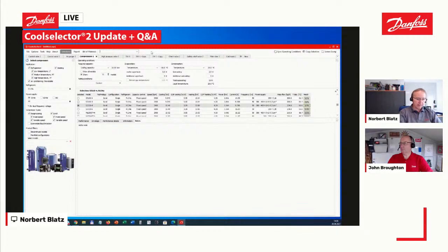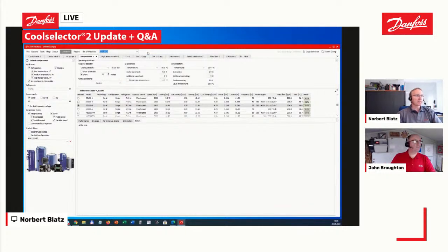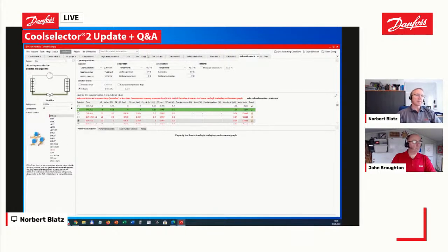And while finding, for instance, an EVR6 valve, I press Enter. It opens up a calculation dialog, taking over your last condition you typed in and provides you with a calculated performance. So if you know what you have and you want to know the capacity, the performance of this, just put it in, press Enter, and you have it. I think that for day-to-day work could be quite helpful.